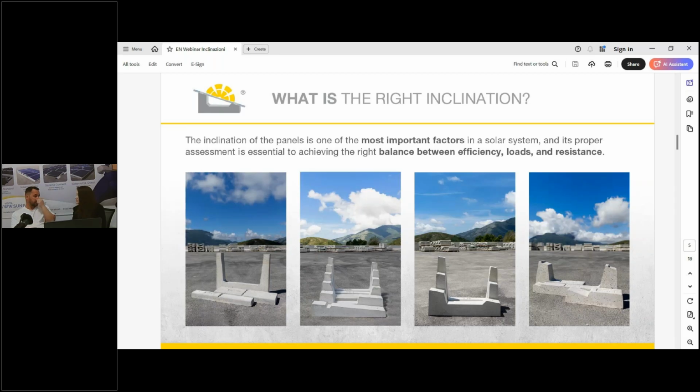And you didn't mention the green roofs as well. Green roofs as well, very common in some countries. Which countries do we have with you? Austria, Australia, Switzerland, all these countries tend to have a lot of green roofs, and they actually always go higher than 10 degrees, and they choose the highest one we have because they want to use the space under the ballast as well.